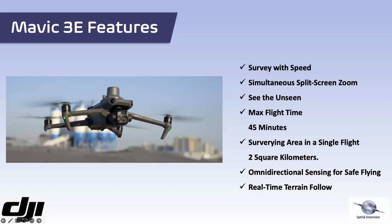The Mavic 3T thermal camera has 640 by 512 resolution and supports point and area temperature measurements, high temperature alerts, color palettes, and isotherms to help you find your targets and make quick decisions. It gives a 45-minute flight duration, which enables you to cover more ground with each mission, surveying up to 2 square kilometers in a single flight.